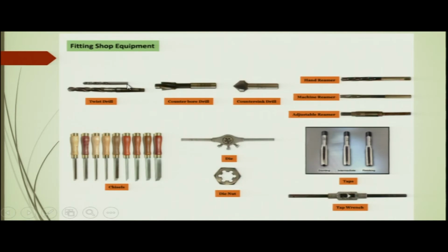So, this drill has to be mounted on a chuck, or a drill holder. This is the shank, which is used to mount the drill in the drill holder or the drill chuck. In this case, you can see that this is the cylindrical shank, and for this drill, where the diameter is more than the previous one, this taper is the Morse taper. The holder for this kind of drill will also have an internal tapered hole with a Morse taper, so that when this drill goes in, the internal Morse taper of the drill holder holds this drill through the external Morse taper that the drill has.